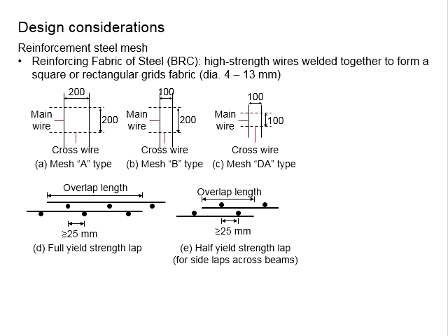Normally, the local industry will put the maximum spacing of the reinforcement bar to be 300. Whichever calculations bring you to a conclusion that the spacing can be more than 300, they will simply adopt 300. That is not right or wrong on these issues, just that the designer chooses to go for a more conservative design.